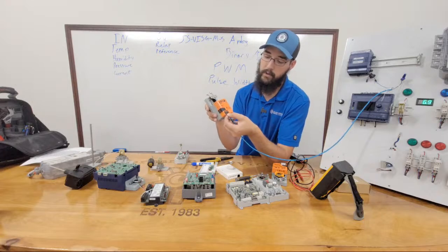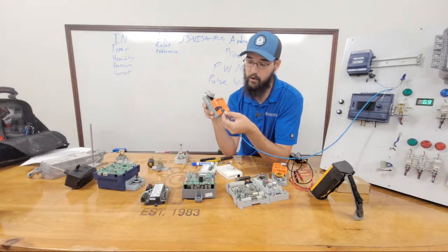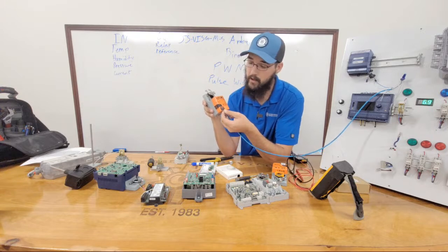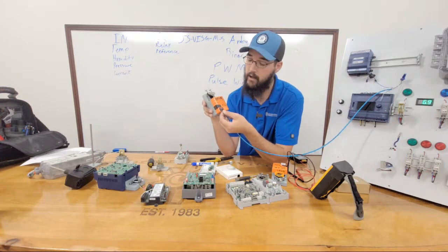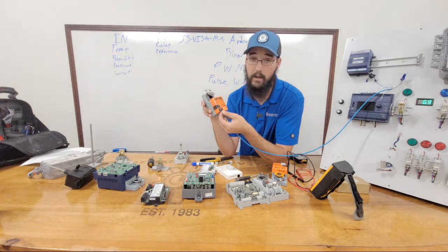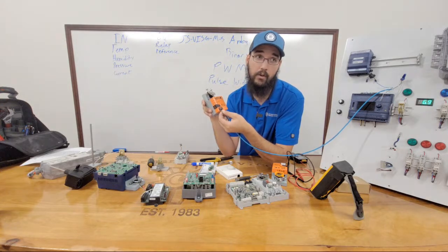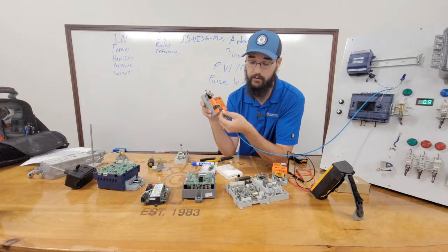And then, so the control system would know, okay, so I want to open X%. I've got a 95-second actuator. I'm going to send 24 volts for X number of seconds, and I'm going to get that percentage. Now, I do not have a reference or anything else. So there's no potentiometer, so I have no idea what position it's actually in. I can only calculate that position based off of how many seconds I send the signal.